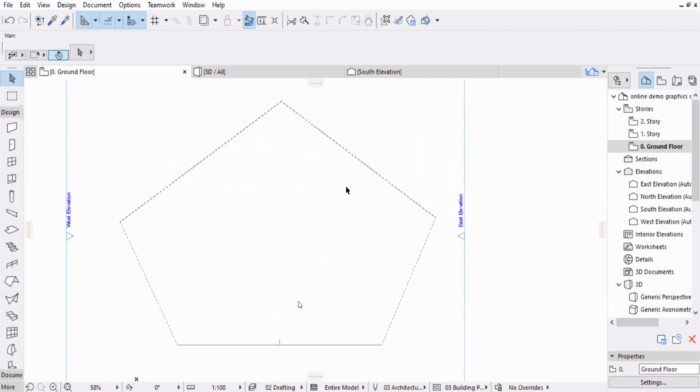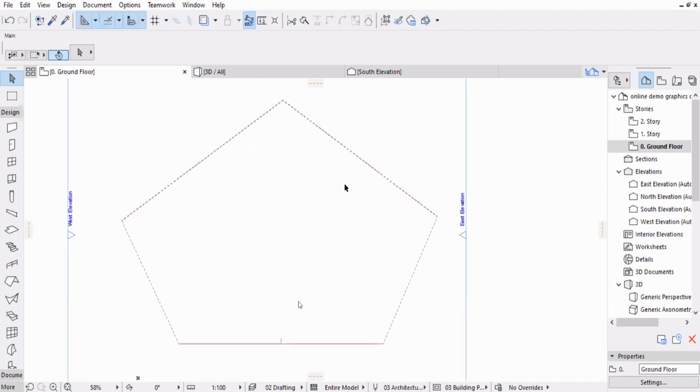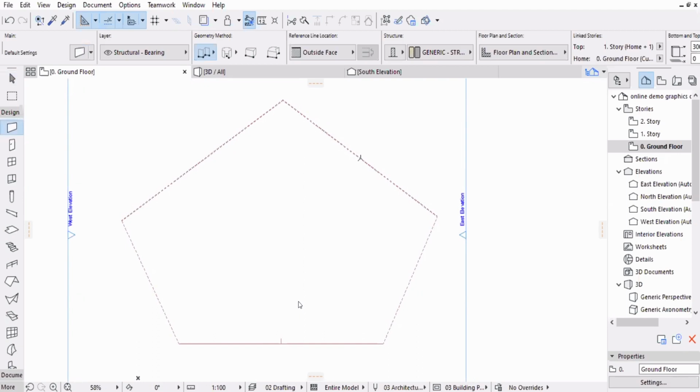But just imagine that sometimes you're working backward, you're drawing the roof, you want to have a specific roof, and then you want to draw the walls out of it, right? So let's draw walls. Click on wall and then just use the magic wand. How do you use a magic wand? Just activate the tool that you want to draw, a slab, wall, or whatever, and then hold down your space bar.